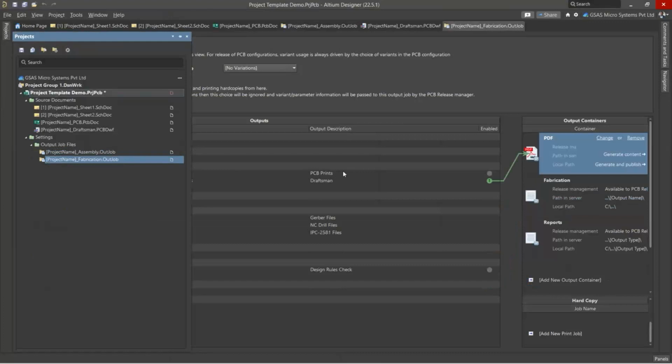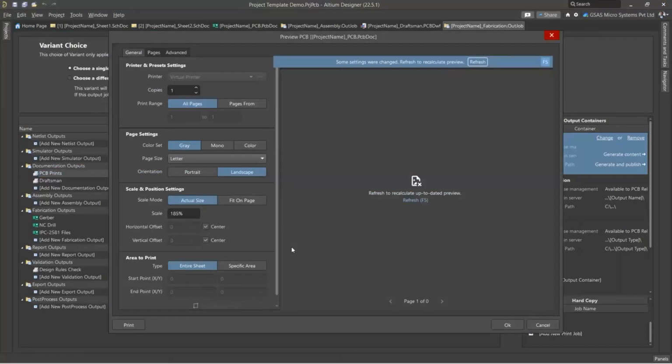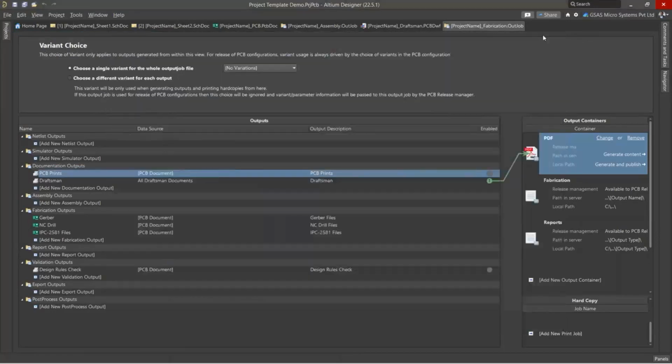You can set those output functions here. The user just needs to cross verify those functions and configurations, whether they are set properly or not, whether they are in the settings. You just need to cross verify these settings and then just click on generate, whether in terms of draftsman documentation or in terms of the control file.